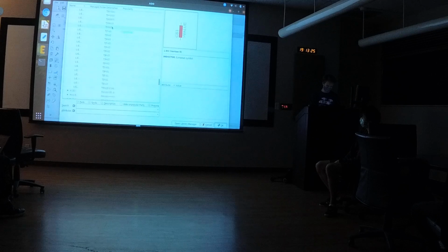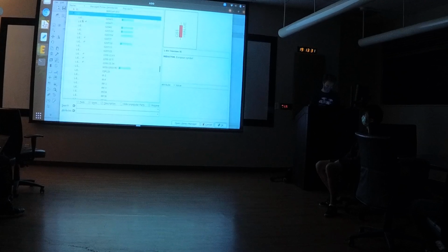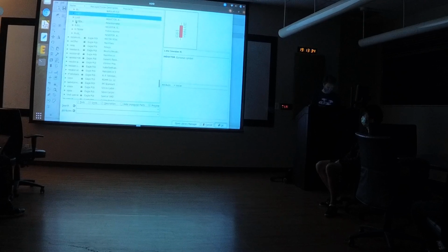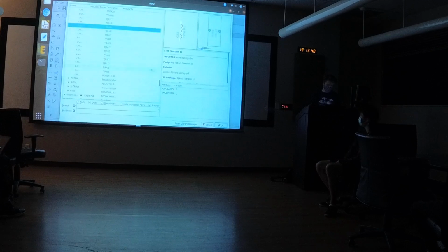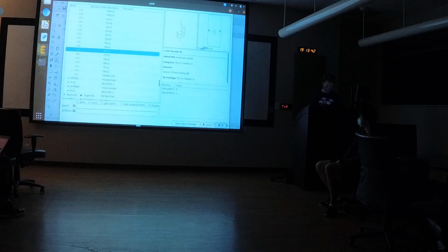So then we go to Industrial European, okay? And you see the packages here are like 0204, 0207, blah, blah, blah. We don't really care about that for now. So we're on 0603, because I think we saved it. We don't have an 0603, buddy. It's just 0204. Let's check the American library. Maybe they have it in American units. You can use whichever one you want. I think I used US. Well, they don't have it in America either.